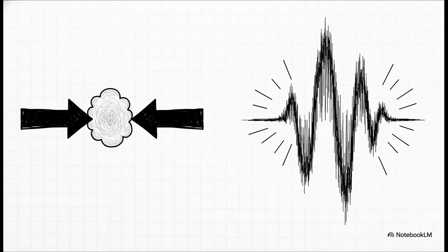And this brilliantly illustrates the mathematical payoff. At resonance, because those opposing reactive forces cancel each other out entirely, the total impedance of the circuit drops to its absolute minimum. At this point, the impedance simply equals the pure resistance. And because the circuit's opposition to the flow is at its absolute lowest, the current amplitude spikes to its maximum possible value. It's just an elegant, powerful moment of physics.